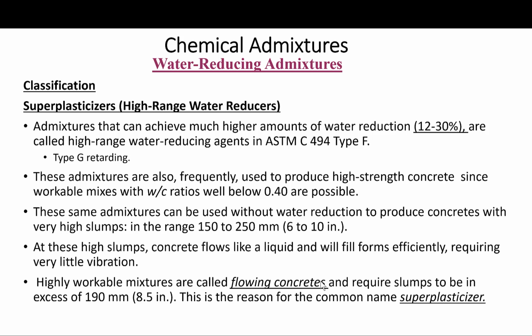Okay, so when used for this purpose as superplasticizer, they must conform to ASTM C1017, which sets a performance limit in terms of an increase in slump, increase of more than 90 mm or 3.5 inches. So there are no fundamental differences between admixtures conforming to ASTM C1017 and C494 specifications, and most commercial products will meet both requirements. The reason for two specifications is the convenience of specifying specific performance criteria in terms of plasticizing effect. So basically, that's just what you need to remember.